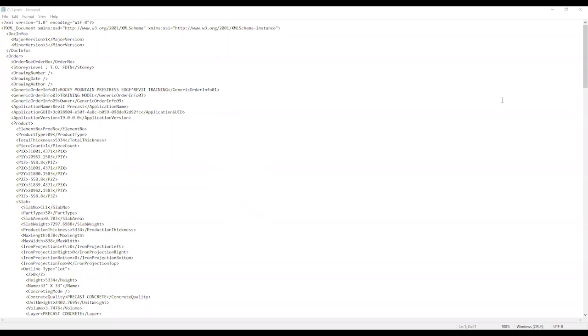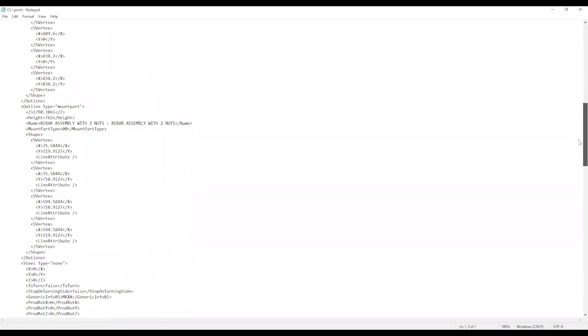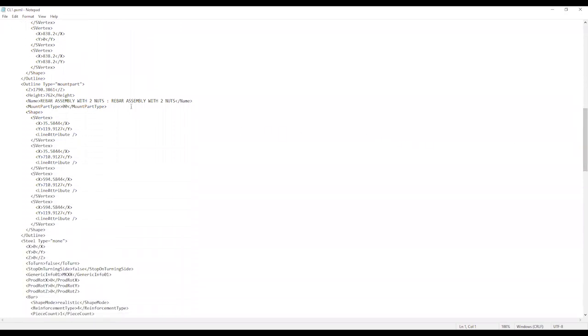All materials such as embeds contained within the exported assembly will be grouped under the Mount Parts section of the exported file. These mount parts will be represented by their bounding box. The bounding box will represent the largest extents of that material. Rebar in some cases will be exported as individual bars, but in other cases must be exported as mount parts represented by their bounding boxes. For more information on how rebar is exported, please reference the CAM Export Help file.